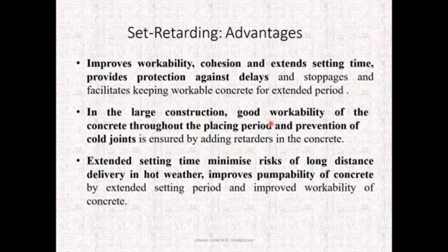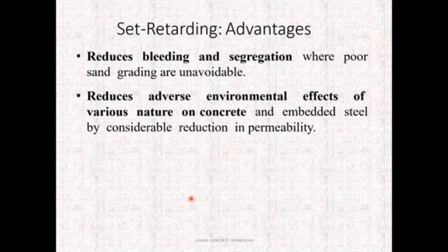In larger constructions, good workability is required. The placing period is extended and the prevention of cold joints is ensured by adding retarder in the concrete. The extended setting times minimize the risk of long distance delivery in hot weather, and improve the pumpability of the concrete by extending the setting period and improving the workability.